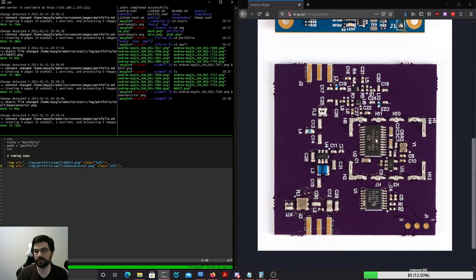That right there is a frequency synthesizer chip. There's a mixer. Actually, I think that might be the... No, that's the mixer. And yeah, it's just a nice little up converter thing. These two are LNAs to get sufficient gain. And then that's the MSP430, which is used to configure the frequency synthesizer.